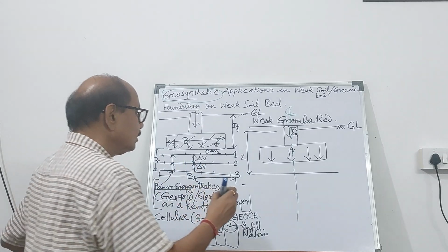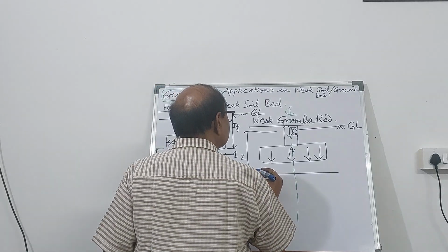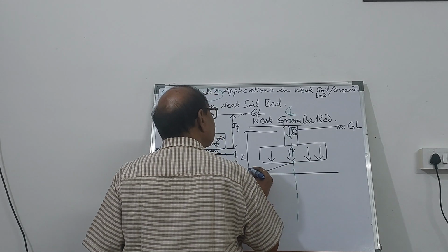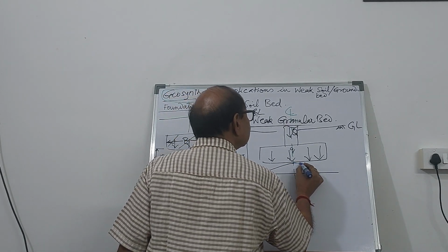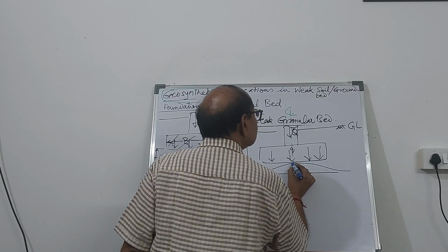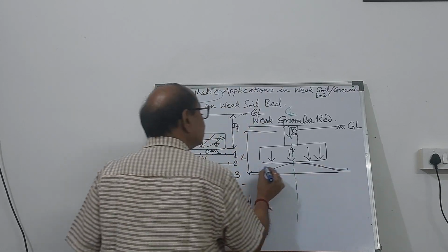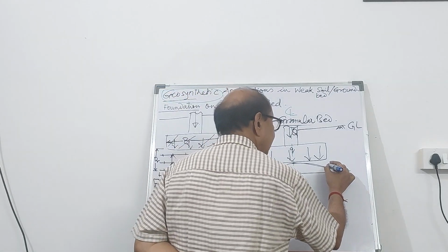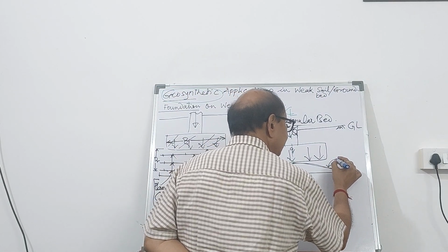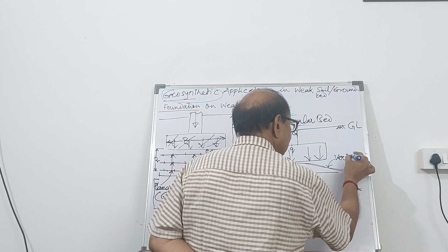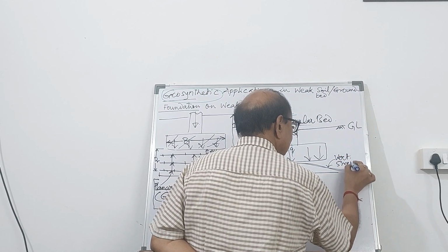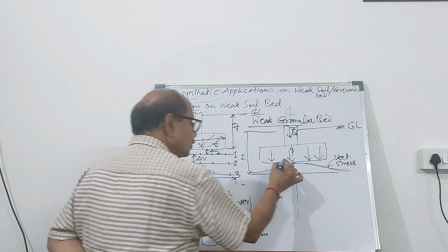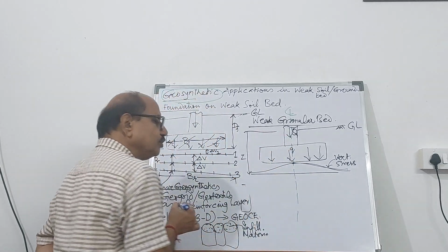And how the vertical pressure is going to change. It's going to be maximum here and then gradually it's going to decrease. Same thing on this side. This is the locus of vertical stress. It is maximum here at the center of the footing.